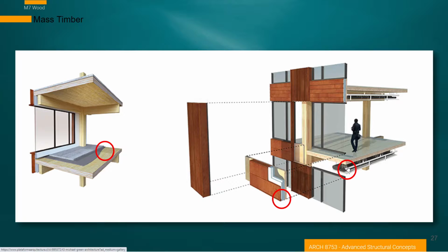So there's one primary consideration with this idea of a mass floor system, as opposed to a joist or open floor span truss system, where you can pass other elements through it, and then you cover the whole thing with drywall to hide it. In this case, you want to see the exposed wood, and it creates another level of complexity, so to speak. The other issue that comes readily apparent is the need to soundproof between these floors.